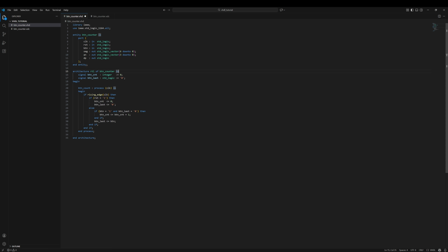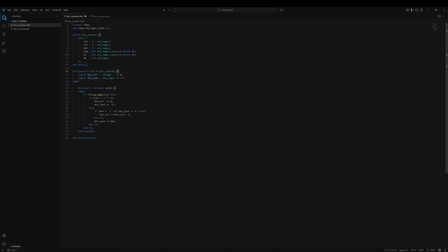Now we could manually turn on the bits in the segment array, but if we ever wanted to change the value displayed, we would have to go back and figure out the new bit value each time. An elegant solution to this problem is to create a set of constant values that map to the available numbers the 7 segments can represent.